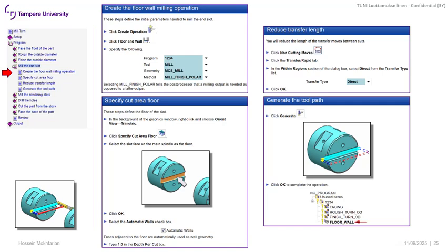For this one, we are defining the cutting area and the wall, and then we are making sure that we define the non-cut movement and also the correct access of the tool itself, so that we first of all machine correctly, with the axis of the tool perpendicular to the surface that we are going to machine, and also save time on idle movement of the tool.